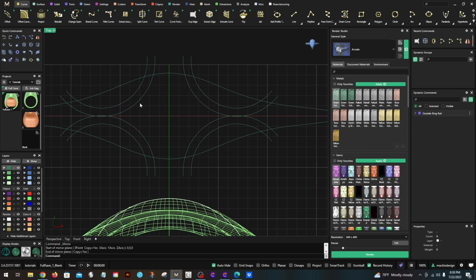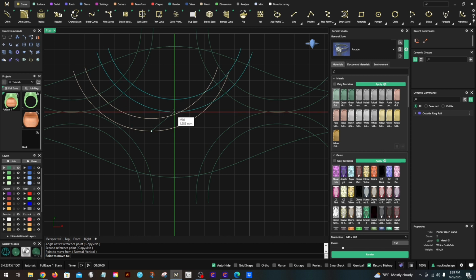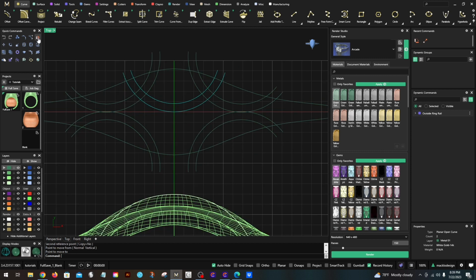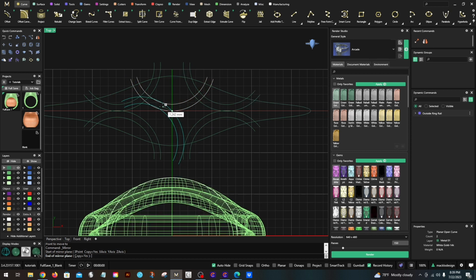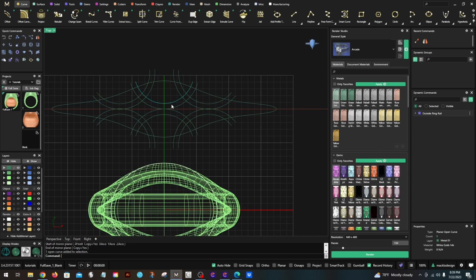And then perhaps we will duplicate this, and maybe we'll just rotate this so that it's straight. Okay. Now I can move it by selecting move, clicking, making sure my O snaps are on, and getting the midpoint. That way I know that the design is accurate. I'm going to mirror that, toggle my O snaps on, and there we go. That's kind of a nice design.